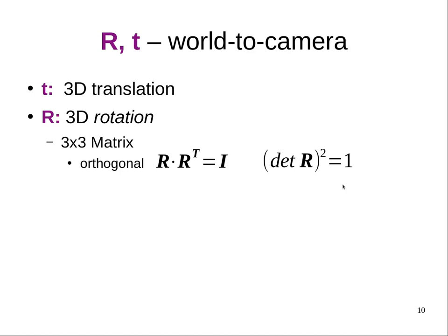The way we further restrict this is by requiring the matrix to be special. Special means that the determinant is strictly +1 and not -1, which is still allowed here. Together these two requirements form a group which is called the special orthogonal group. Because we are talking about 3x3 matrices, it's the special orthogonal group of 3. And now we arrived at a 3x3 matrix which only has 3 degrees of freedom.